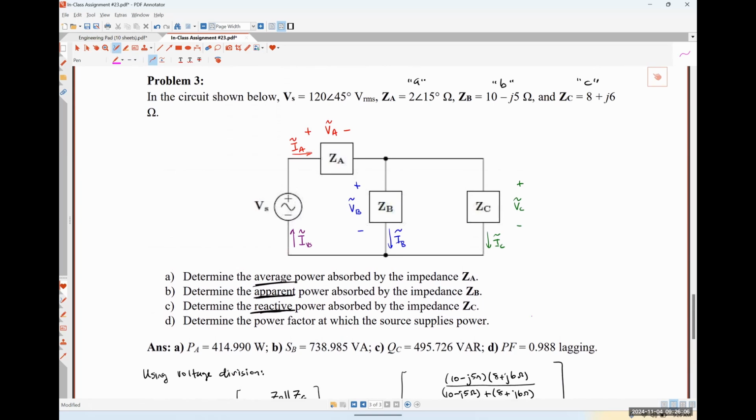I'm going to do that calculation up here since I ran out of room at the bottom. So we could say that IA is the exact same thing as the IVS that we're looking for because they're the same current in the same direction. So no need to do anything fancy there. The complex power for my voltage source is just VS times IA conjugate.